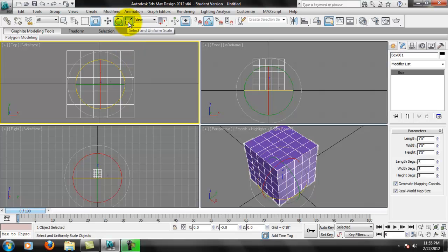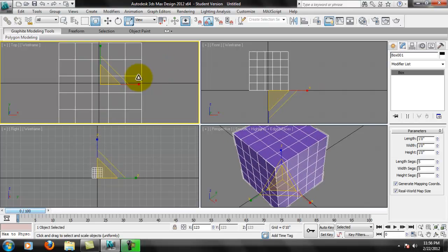Okay, the next transformation tool is the scale. Anytime you see a little arrow in the lower right hand corner, that means you can click and hold and there's more options. So some of these have more options hidden in them. These are basically different types of scales. You have your uniform scale, non-uniform scale, and this scales in both directions. I can't remember what the name of this one is off the top of my head. Basically, you can see that it scales in individual directions. Or this scales by the corner. So if I wanted to scale this box uniform, I would select the middle triangle.